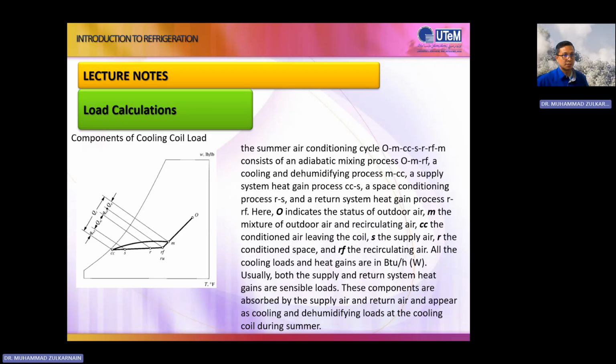So from this condition, as mentioned in the graph, you can see it will experience different temperatures. During the transfer, the temperature has already changed. You can see the CC has a lower temperature from the coil, and then by transfer to the S, the temperature increases, and then by serving the room, the temperature becomes higher. So this is serviced to the occupant at the temperature of RF.